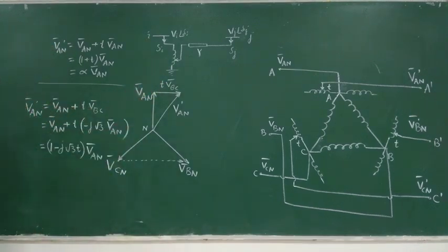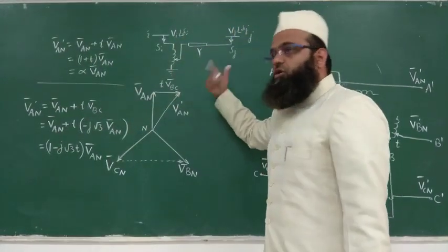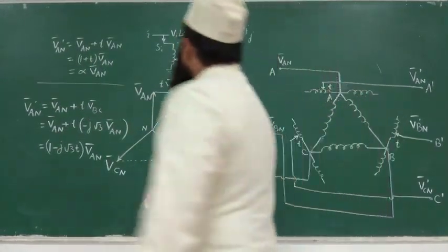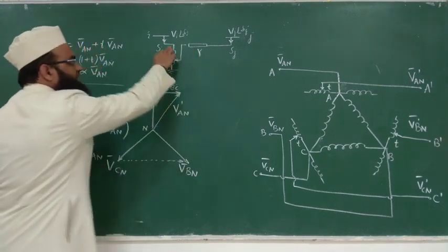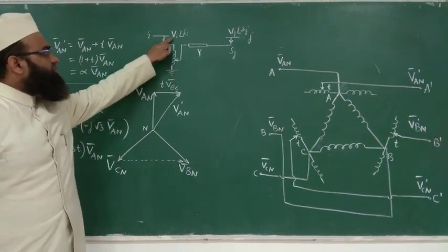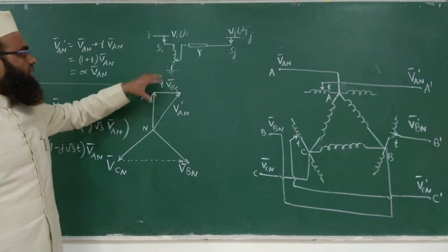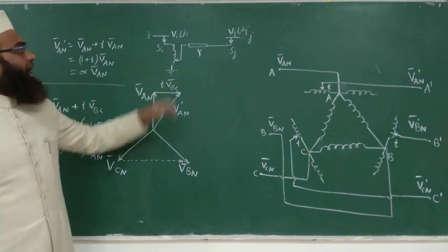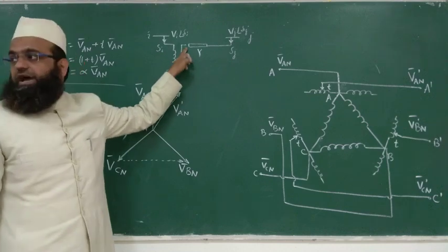So this is the representation of a voltage control bus controlled by a regulating transformer. So the potential of this will be different from the potential here, is it not? The potential here was Vi angle delta i, and you are going to use a regulating transformer, which means you have controlled Vi and delta i both. So both have been changed here at this point.